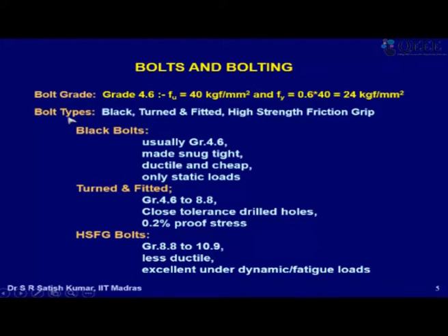Then in terms of their behavior, they are classified as black bolts, or from the behavior point of view, they are called bearing bolts. That means they transfer the load by the bolt bearing on the side of the hole. So the minute I put a bolt and I pull, the bolt will bear on the side of the hole and it will transmit load.